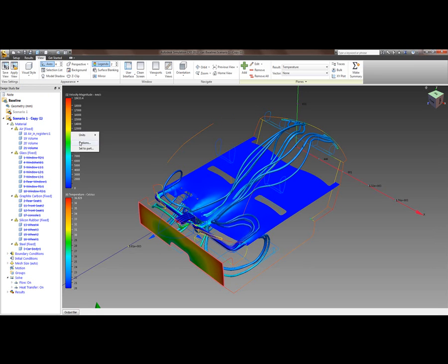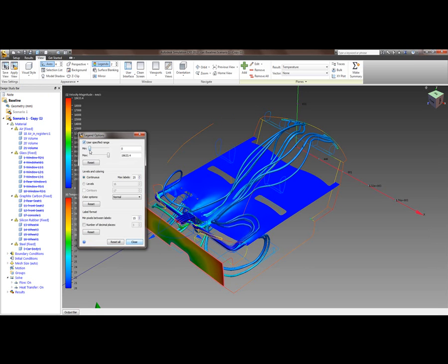And you can notice from here at the back, so if we go into our legends, I could focus this up a little bit so we can just see. You can see now it's getting warmer towards the back of the car. So the back of the cabin is where the heat's coming through. In order to address this, perhaps we could add some additional vents behind the seats, just in order to keep the passengers in the back a bit more comfortable.